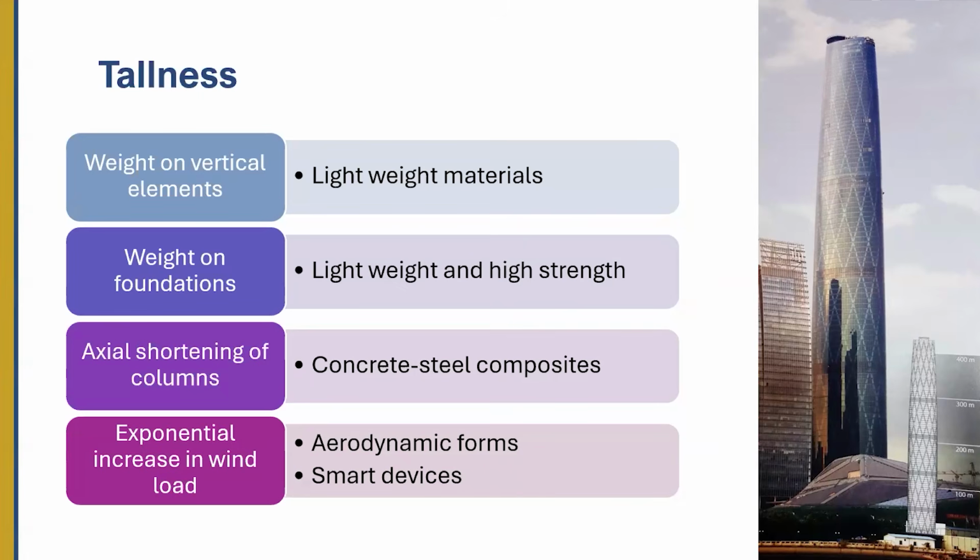So the slabs are made like this in theory, and then they come down. But in practice, we are just making those corrections on every floor, right? So this is very complex. And this changes the distribution of loads, distribution of bending moments, everything in the building. And that's why one of the important things that we need to do to handle that is the construction sequence analysis, nonlinear construction sequence analysis, which we will learn to do.